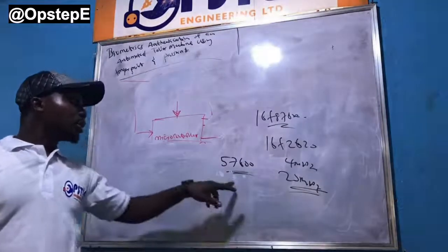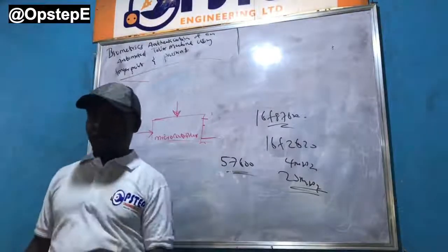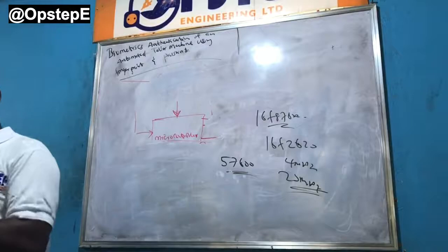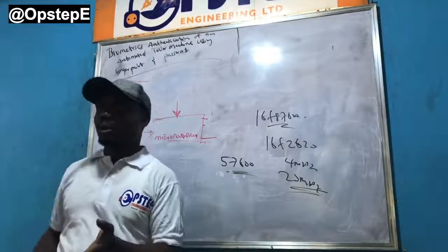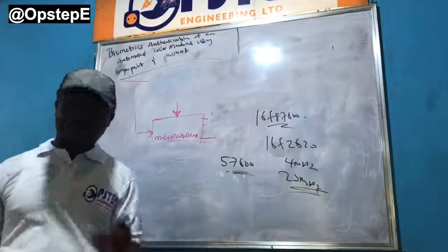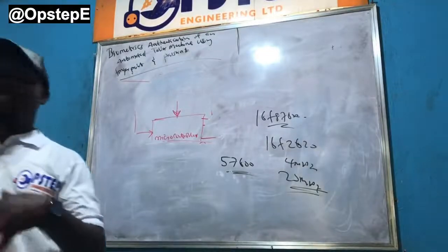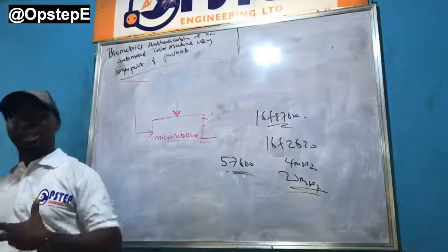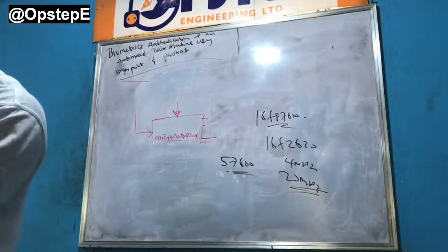Okay, now the truth is, this is what you do. Get your microcontroller data sheet and go to the part where baud rate is discussed. There's a formula with which your baud rate generator works. There's a baud rate generator in the controller that determines what baud rate you can use based on the crystal.